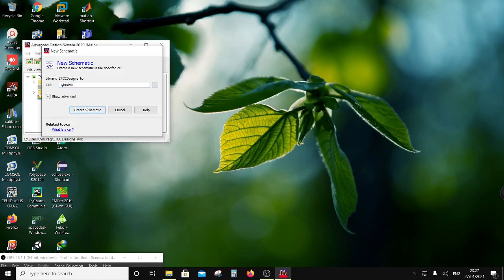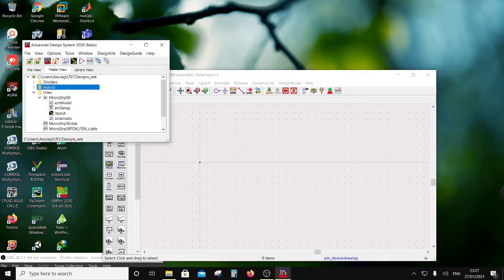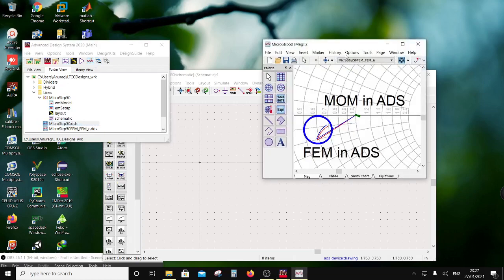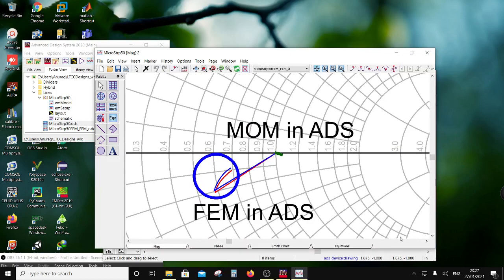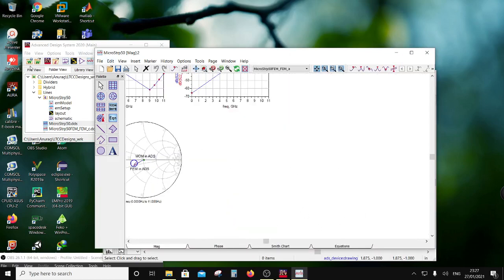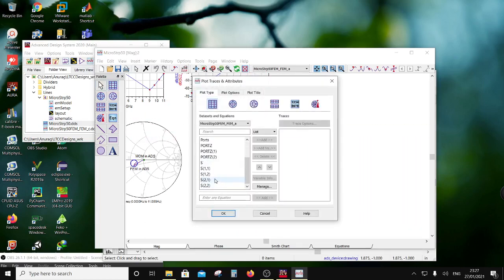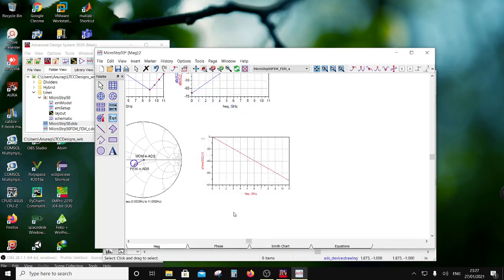Now what I'm going to make sure is that I design this line. Forget about the EM simulation or whatnot, I just want to see whether the line is 90 degrees. So I will plot the phase of S21 and make sure it is a 90-degree line.